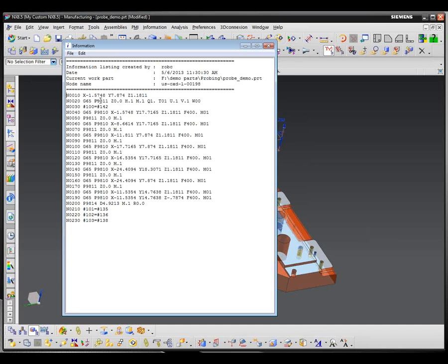It outputs the 9811, which is a probe move. Then this is the output for it, and then each subsequent move after that is a 9810, which is a protected move to the position. Then it goes into the 9811 probe routine. And what you would want to do is insert this code, the 100 equals 142, in behind each one of these 9811 probe routines. And then later on, you do some manipulation with those, either averaging them all together and setting your coordinate system equal to that average, or correcting your coordinate system by that average.